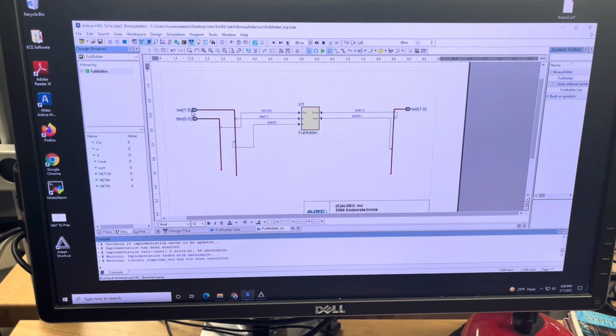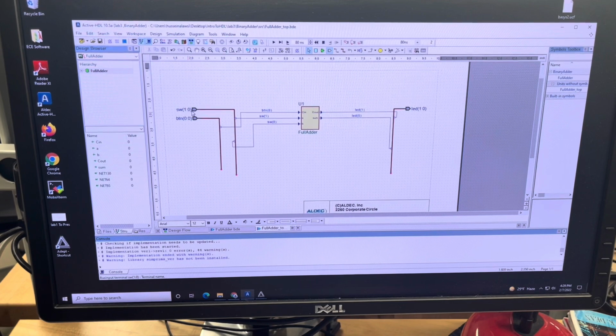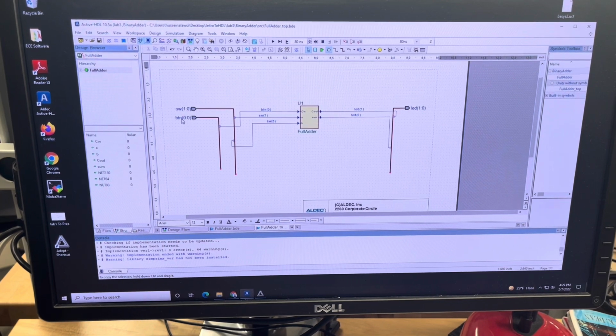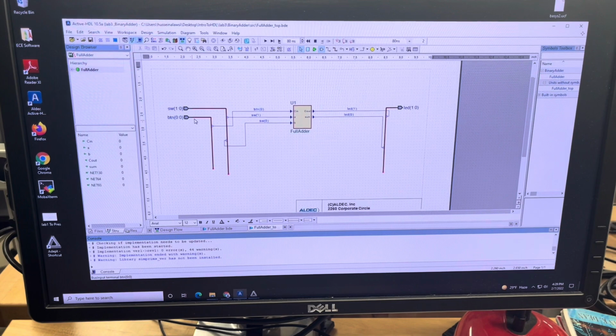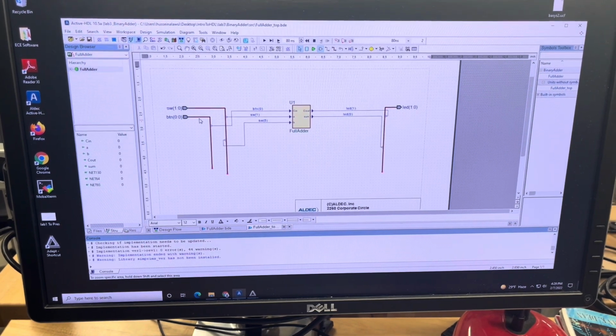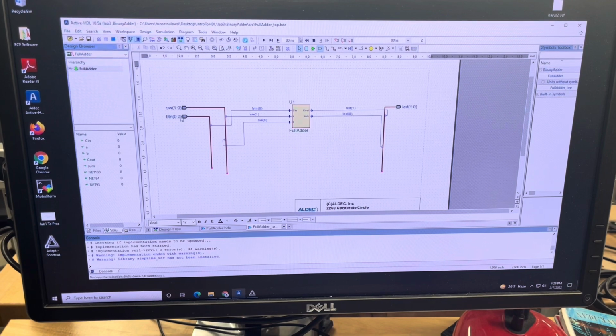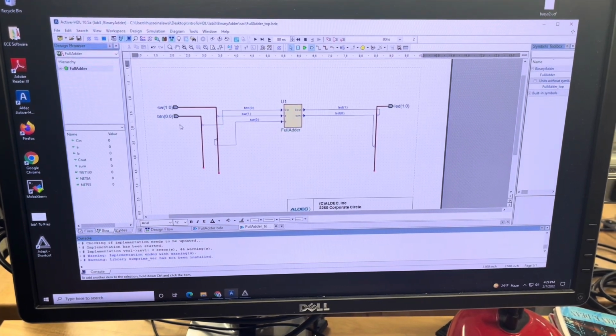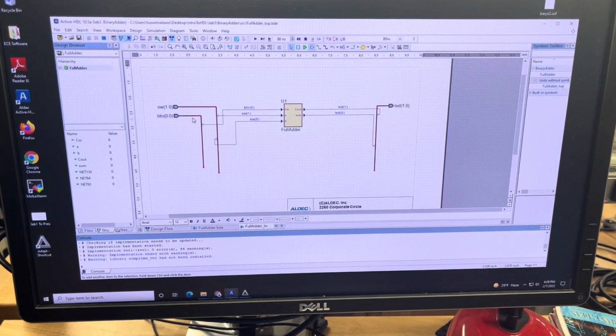If we have SW[3:0], that means we have 4 inputs, or 4 wires in that bus, which are represented by SW3, SW2, SW1, SW0, and so on. This bus down here, which is BTN[0], is represented by just a single wire inside that bus, as we can see here, and it's connected through the blue line.